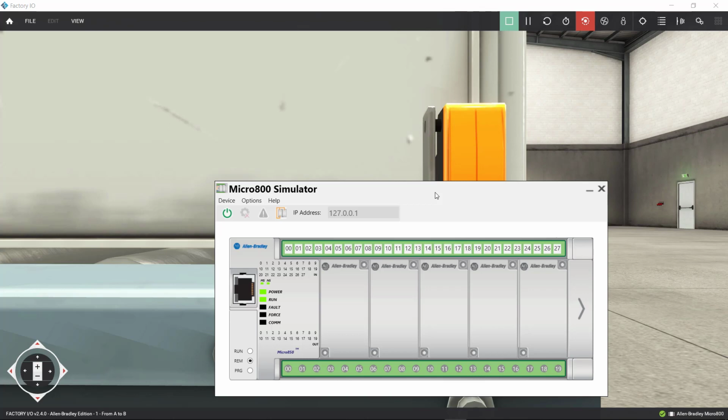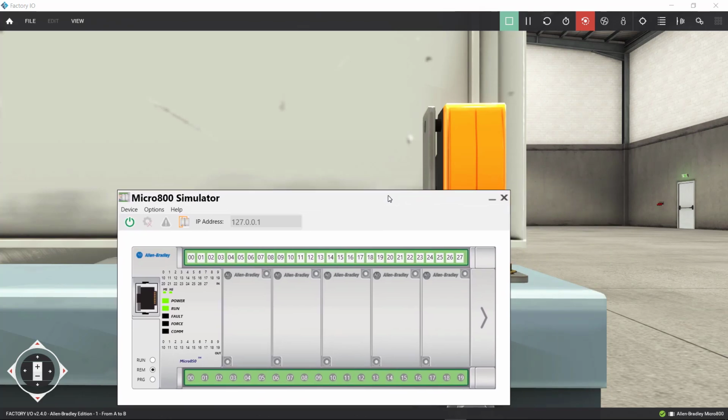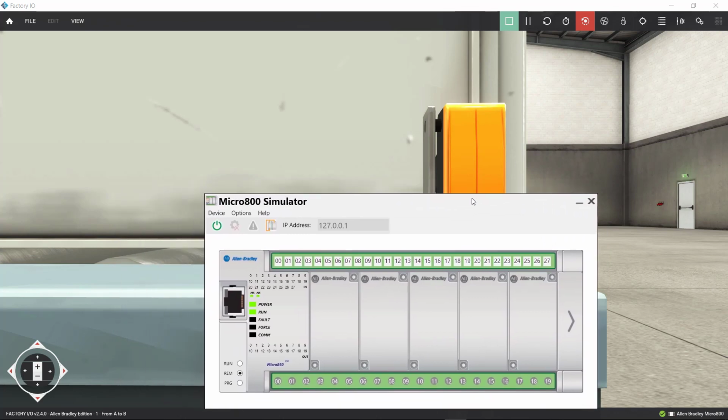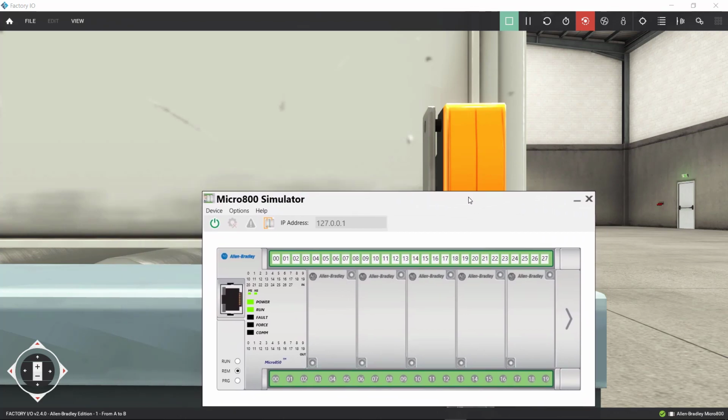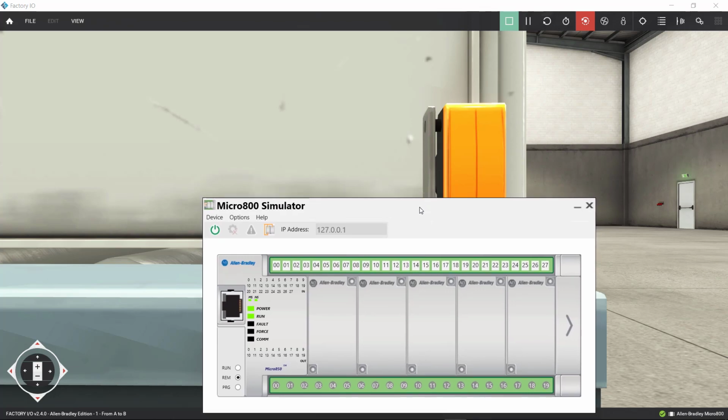Take that into consideration when you are programming. Sometimes the load is going to stop a little further behind, or a little further in front. Actually, it's not going to be in the exact position all the time. So take that into consideration and program your way around it, and it's going to work just beautifully, all right?